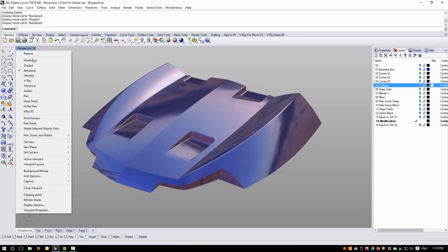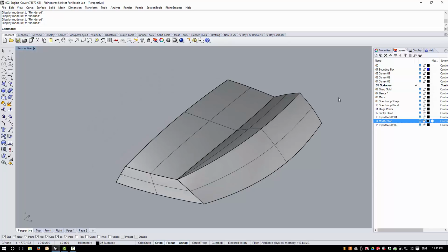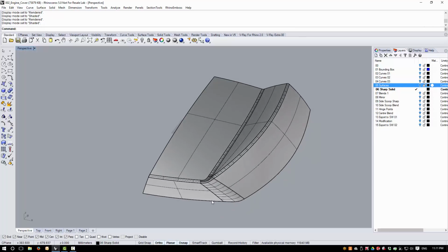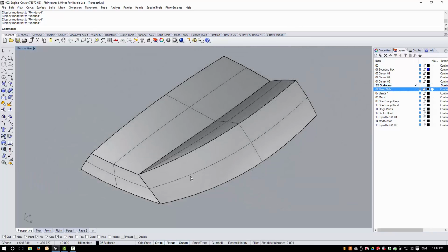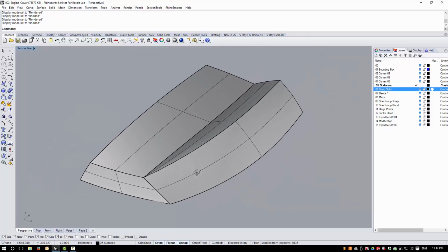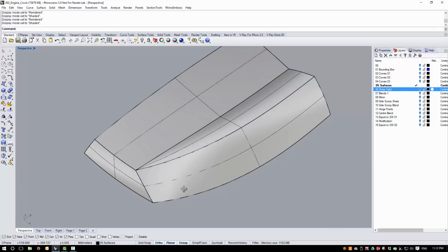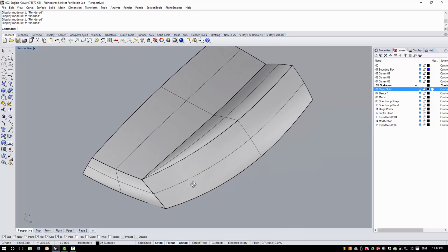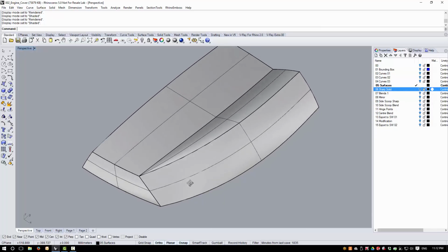In this first video, we're going to quickly examine laying out 2D and 3D curves to create the basic slabs that we see here, before moving on to look at creating the main blends and in particular this slightly difficult front corner transition. Going back to the overall geometry, the shape around this front corner is less than ideal for a smooth result. And we've done this purposely so that we can look at the methodology we can use in these real-world situations where we need to build smooth transitions on geometry that doesn't really fulfill an ideal.